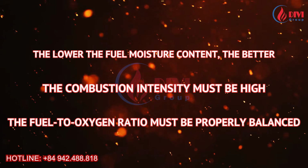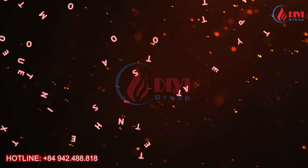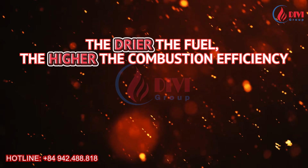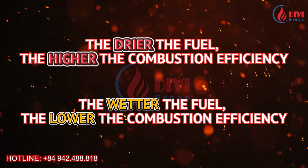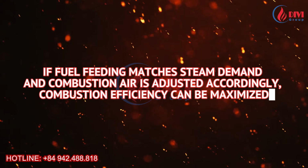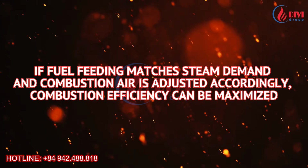Among these factors, fuel moisture is the one operators can most directly control. Therefore, fuel moisture should be kept as low as possible. The drier the fuel, the more efficient the combustion process. The wetter the fuel, the lower the combustion efficiency. In addition, if fuel feeding matches steam demand and combustion air is adjusted accordingly, combustion efficiency can be maximized.